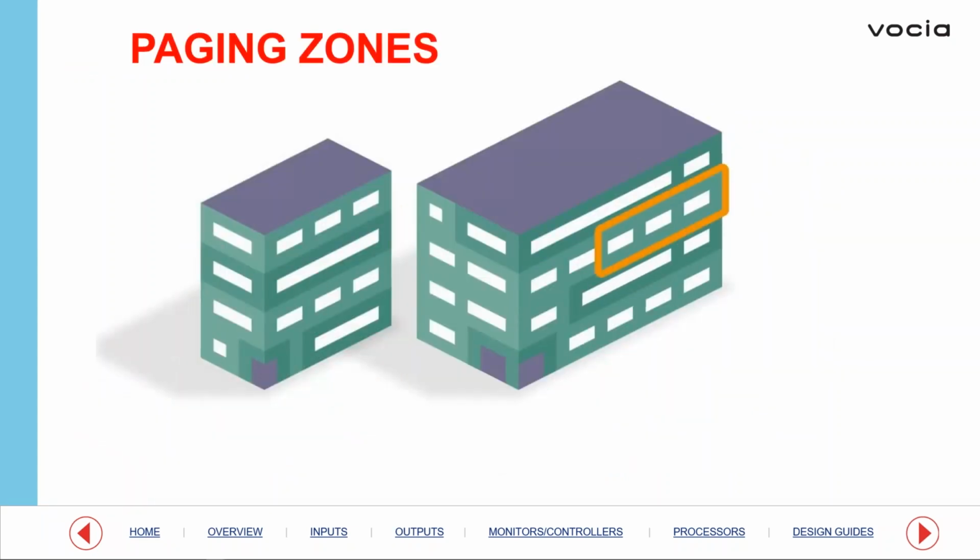So now let's talk about paging zones. Paging zones is literally, I could slice out a piece of the pie, and that means that particular floor, it looks like the third floor of that building on the right, is a zone. Somebody could identify that, hey, that area needs to be handled separately or a little bit differently. And so that zone literally would be physically wired differently. It would have a set of speakers, it would have a cable that ran back to one of our amplifiers, and we would identify that as a very unique zone.